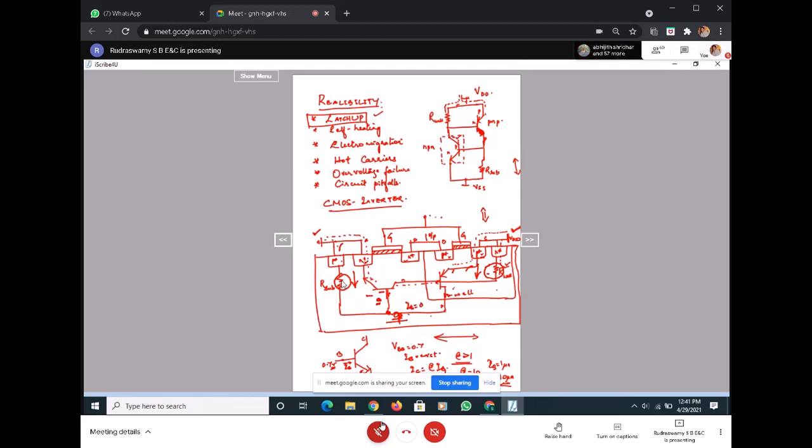In turn, the collector current or the base current for this becomes 0. The moment the PNP base current is 0, automatically, even if I have not reduced my R well, that is still no problem for me. I have to ensure one transistor is off. That's it. I can reduce R sub and ensure the transistor doesn't conduct. That's it.